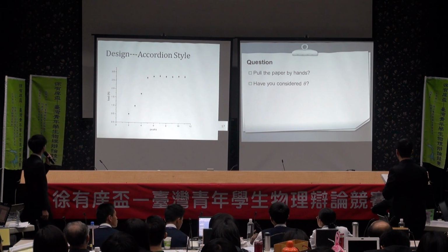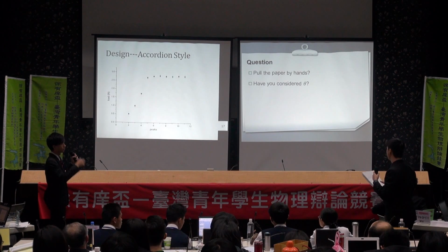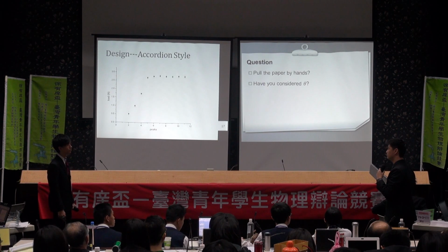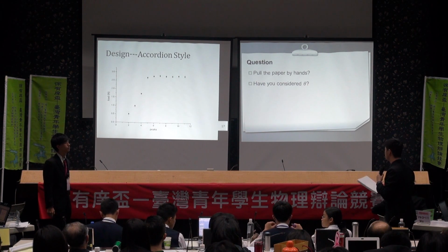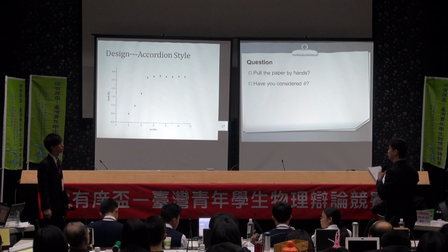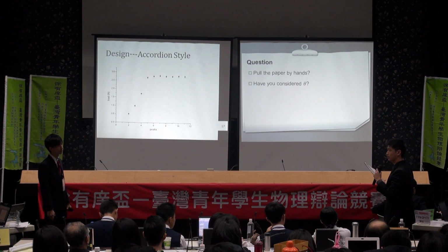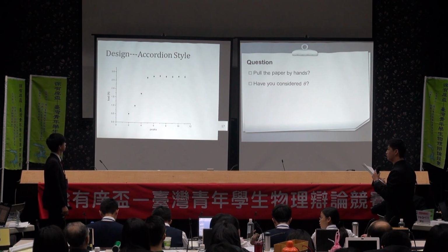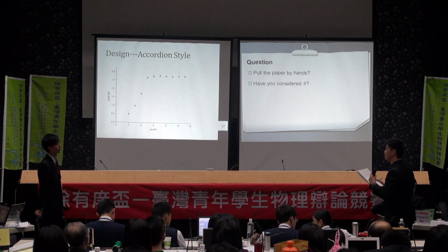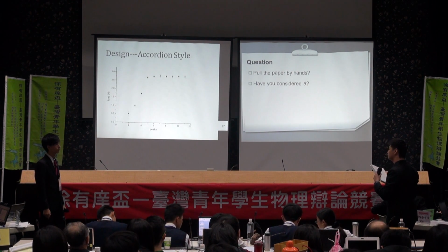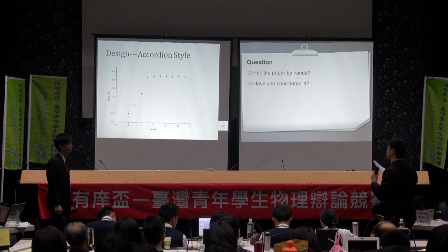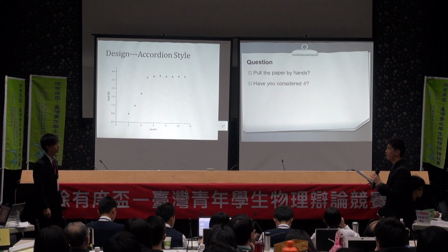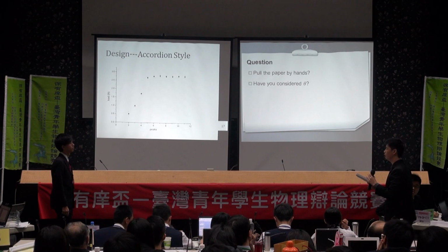Have you calculated, do you know that there are two kinds of buckling? No. There are two kinds of buckling, one is long column buckling and another one is short column buckling. There's a condition for when long column buckling can be used for the load force, and otherwise you cannot use the formula that you gave. First, you need to know whether the slenderness ratio is bigger than the column constant. Have you calculated both ratios?